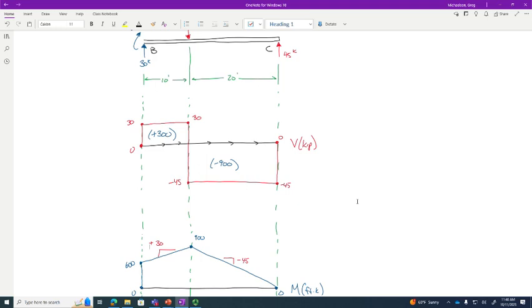So what this is going to mean is this: I'm going to be able to sum up some terms. For moments, instead of little f and big F, I'm going to have little m and big M. Instead of EA, I'm going to have EI. But instead of being able to just multiply by the length, I actually am going to have to integrate. We're going to have to do some calculus because we're going to be summing up the energy across the span, and unfortunately, the energy is a function of the moments, and the moments change. So we actually are going to have to break out some integrals. That's the bad news. The good news is that the integrals we have to do are really, really easy.